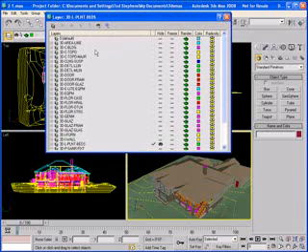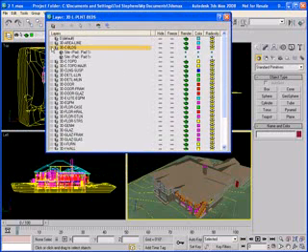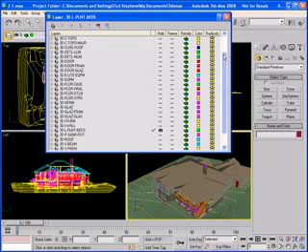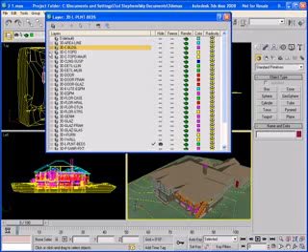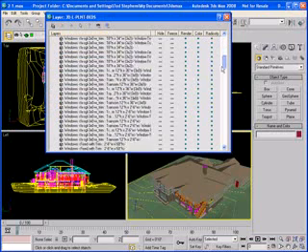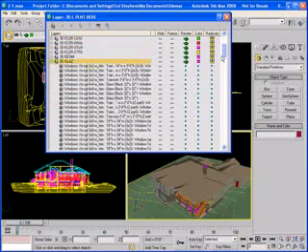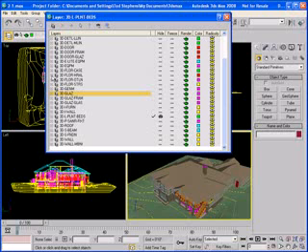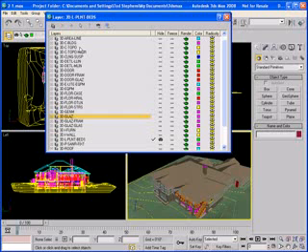Now I'm going to go under the Layer Manager. Here you see under each layer, when I hit the plus sign, I can see all the different objects that are inside that layer. There are a lot of windows from Revit that were brought in, each one labeled individually. Each of those is a different object I could select, and then I could put materials on any particular window.